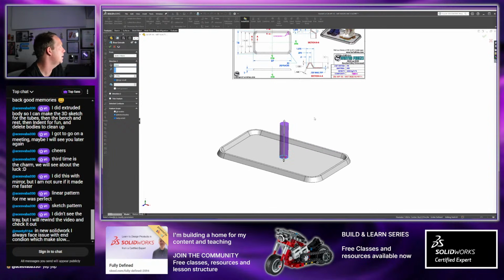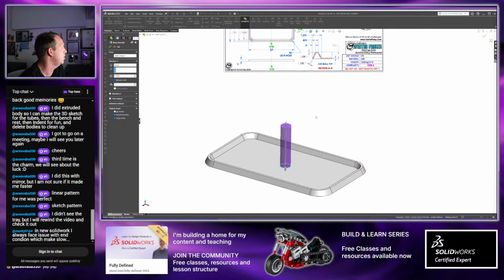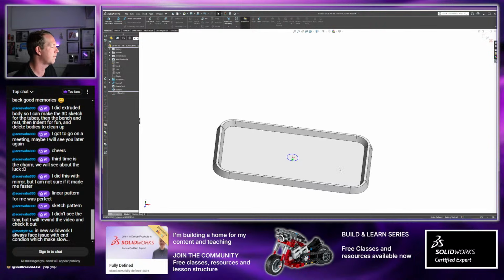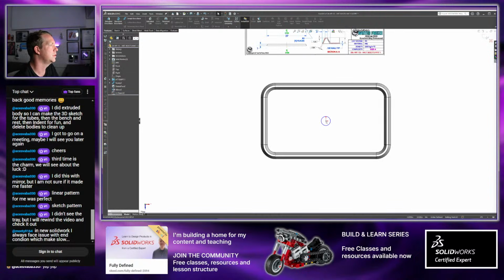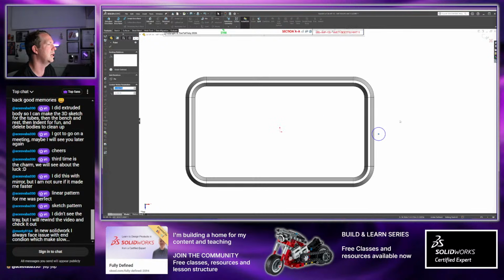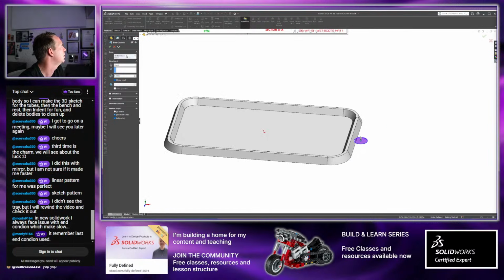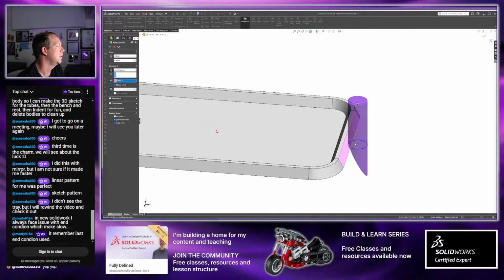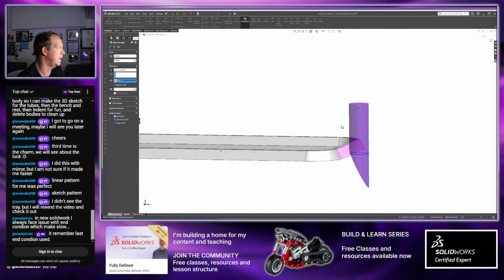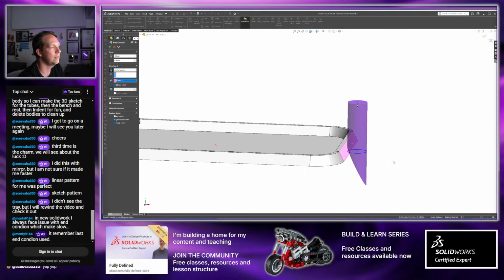Also, the type of sketch that you have can be an issue. Let's say I was doing a circle here and I'm trying to do an extrude, and it's offset up here and I want to come down and go up to surface. Depending on that, if I'm trying to use a surface as an end condition, sometimes that can cause issues if it makes a geometry that's not going to work.